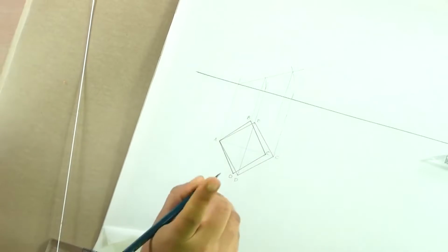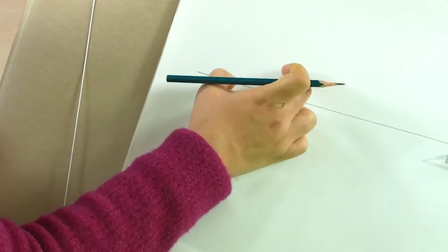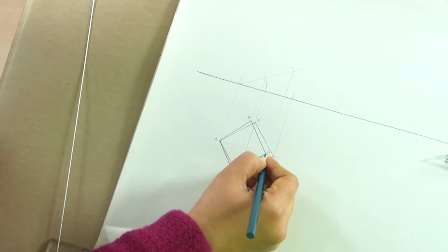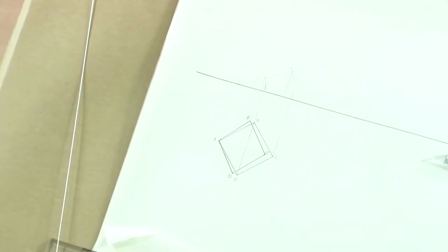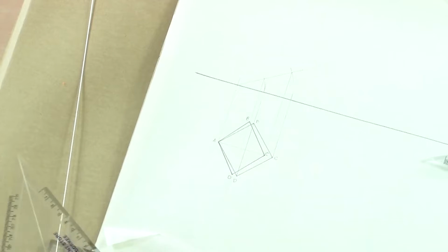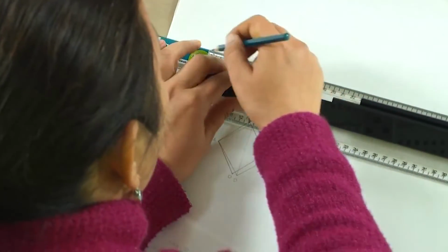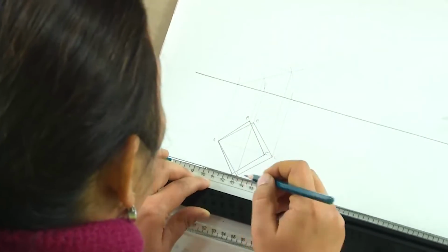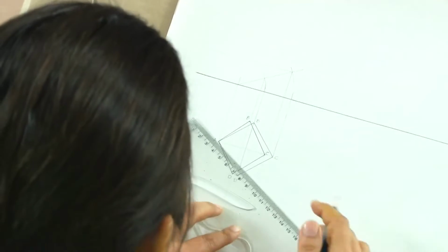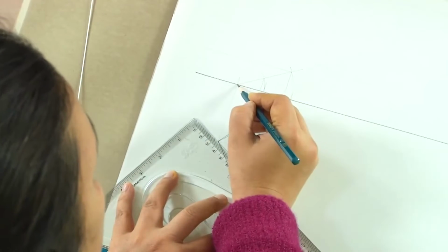Now, in this case, what we have seen is that this diagonal AC is still seen in true shape, and that is what we are getting here. So, this is the reduced shape. Now, this AC is going to make an angle of 30 degree with VP. So, what do we take here? So, I am just drawing the horizontal projection. We will draw an angle of 30 degrees with VP now from this point A, which is in HP.